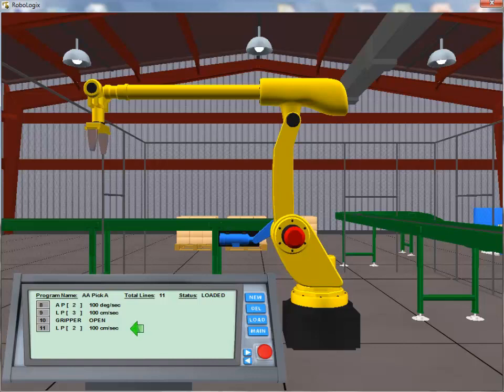This is accomplished by adding another linear motion instruction and referencing the index number we selected when we initially defined that position. With the robot arm and TCP clear of conveyor 2, we add the home instruction to return the arm to its original point of origin. Lastly, we add the end instruction signifying that the program should be terminated at this point.